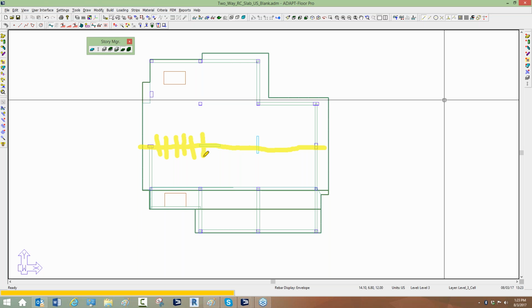For example, if I have a design cut here which extends over this wall, the program only calculates the minimum service reinforcement for that design cut versus the strength rebar. So if we have two cuts on either end of a wall, many times we're going to have a demand moment which might be a negative peak, and then it drops down, and then a peak, and then something like this. It looks like Batman here. So at this moment, this is a negative moment and a negative moment.